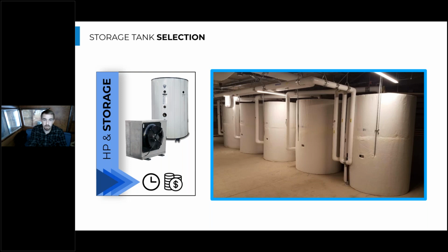Because these heat pumps, as I mentioned, like pulling in really cold water and outputting hot water, and the way we set up the storage will drive that a lot more efficiently and allow these heat pumps to always bring in that cold water, and also have the nice long run times that heat pumps like, because they don't like turning on and off really quickly.